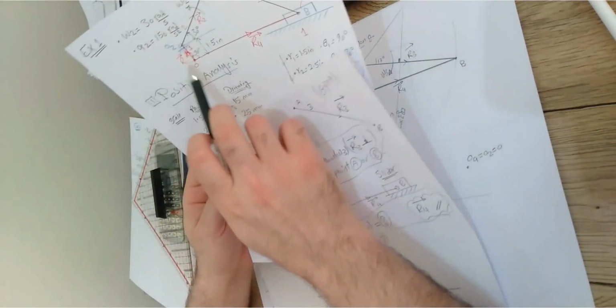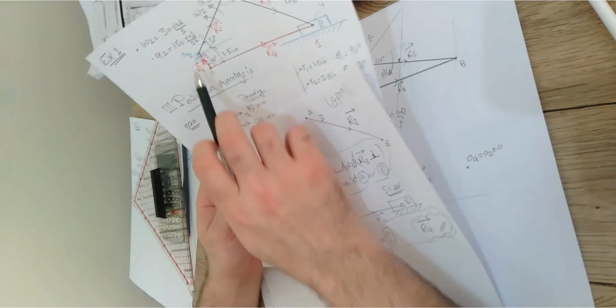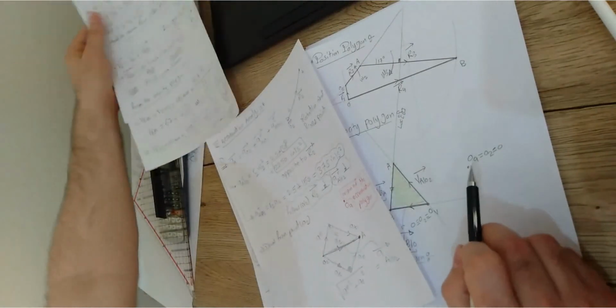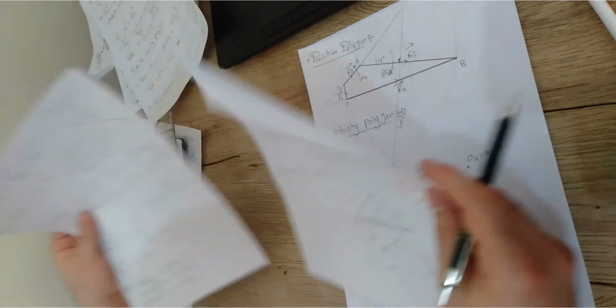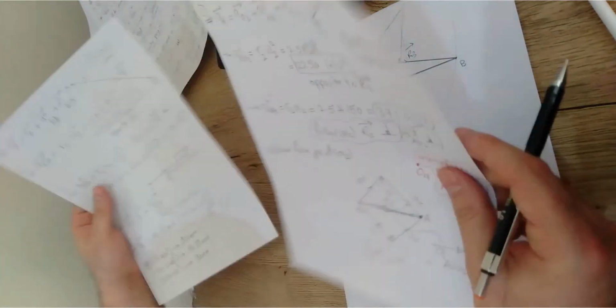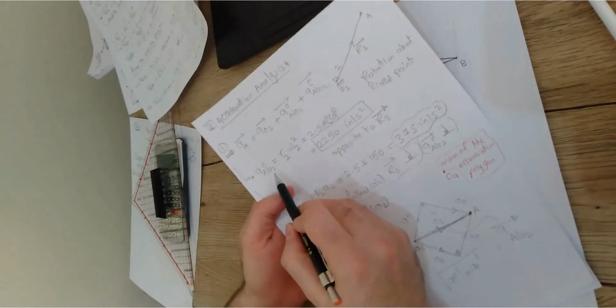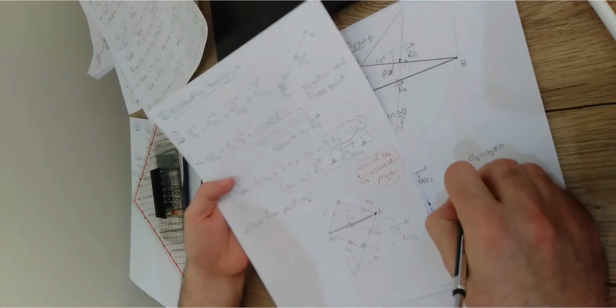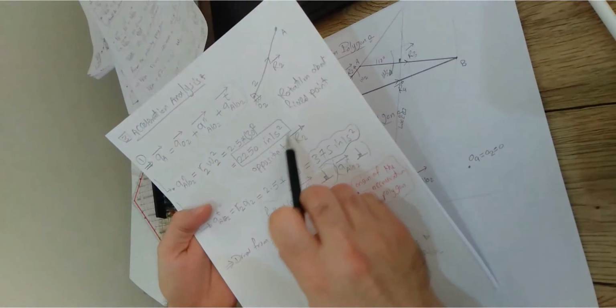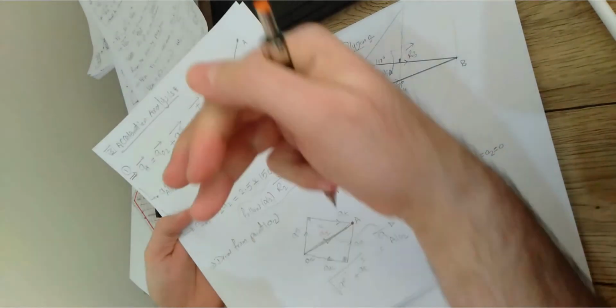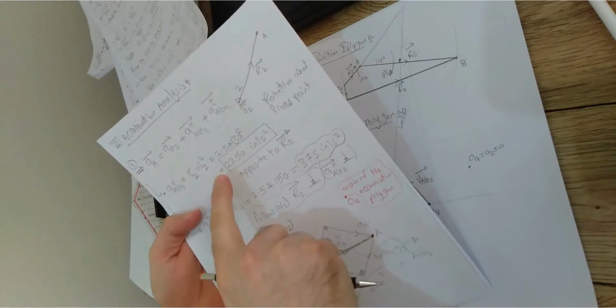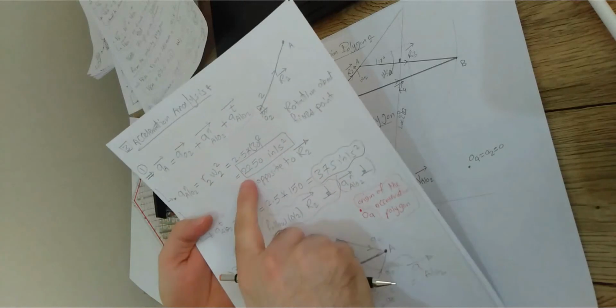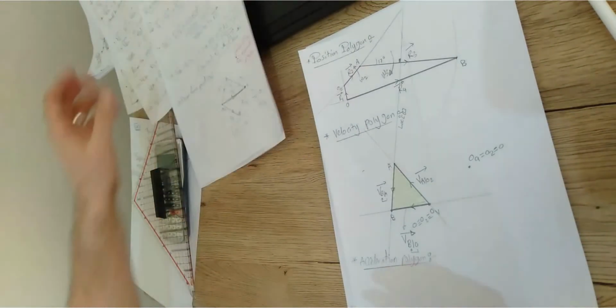These two fixed points with zero accelerations, O2 and O, will both be over the origin point of the acceleration diagram. So this one should be drawn from O2. I already have O2, so starting from this point, I'm gonna draw a line opposite to the R2, parallel to the R2, but going in the opposite direction. And the length of this line should be 90 millimeter after the scale.